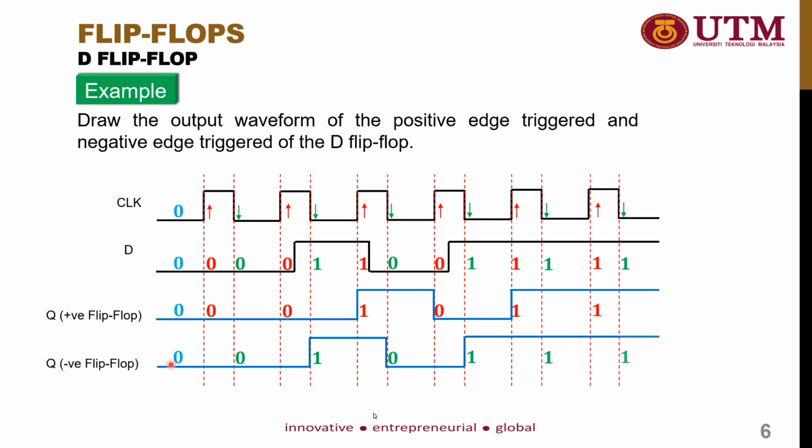Okay, so you must be aware of the type of flip-flop, whether it is negative or positive edge triggered. If it is positive edge triggered, you observe the rising edge, and if it is negative edge triggered, you must observe the falling edge.